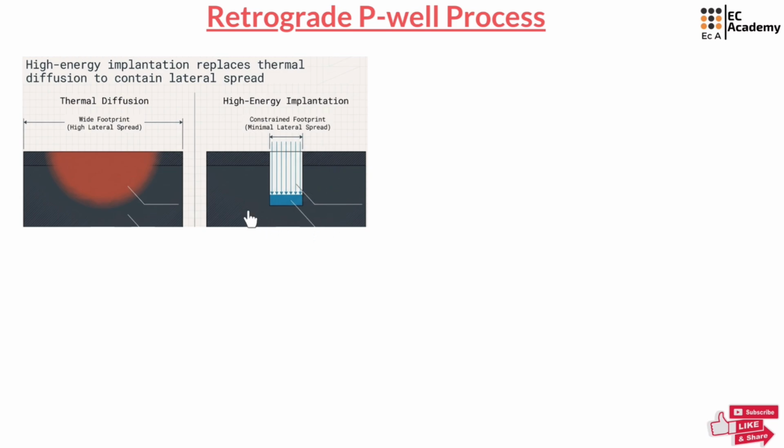If we have more transistors in this less space, we will have faster and better transistors. So using this new method, we can control three important things. First one is junction depth, then the sheet resistance and the threshold voltage. All these three can be controlled independently, which is a very high advantage of the new method.